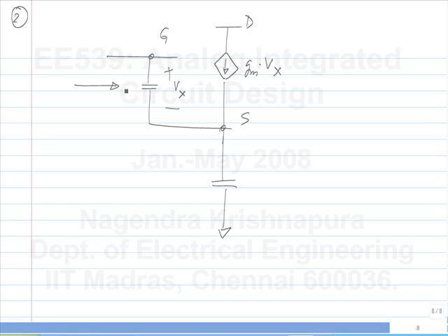It's because of the current source, and one way to see it, it's sort of contrived, but if you force a current I, it produces a voltage V that is 90 degrees lagging from the current I. And this voltage produces a current. So, if this I is at 0 degrees, this voltage will be at minus 90 degrees.